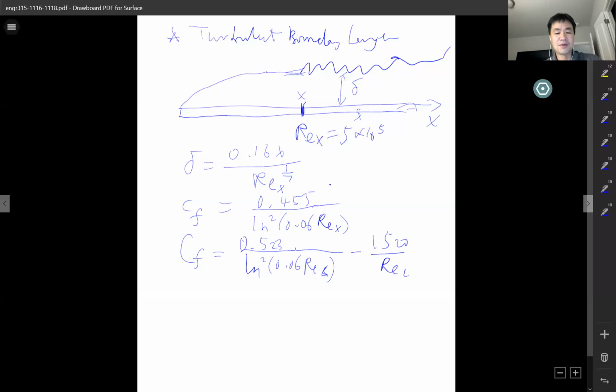So on the flow side, you should be able to calculate everything based on this. We had the example before, right? You should be able to calculate the overall shear stress, overall shear force, the resistance force of the plate. This equation, including this CF equation, is for the entire plate.